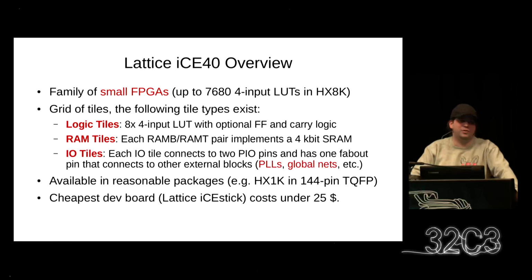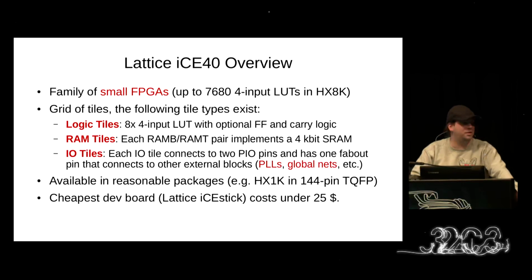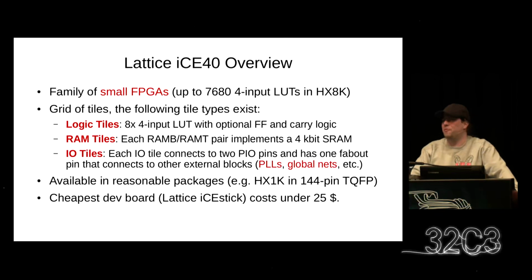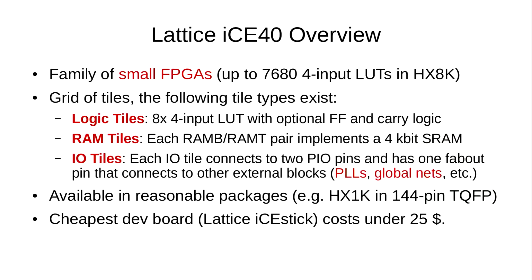First, I think I should give you a little overview of the iCE40 FPGA series, because the iCE40 FPGAs are not very widely used. I mean, a lot of people use Xilinx devices or Altera devices, but Lattice iCE40 is kind of niche. So it's a family of small FPGAs. The largest one has a little bit under 8,000 LUTs, and the LUTs are small 4-input LUTs. The FPGA itself is, of course, a kind of grid of tiles and different kinds of tiles.